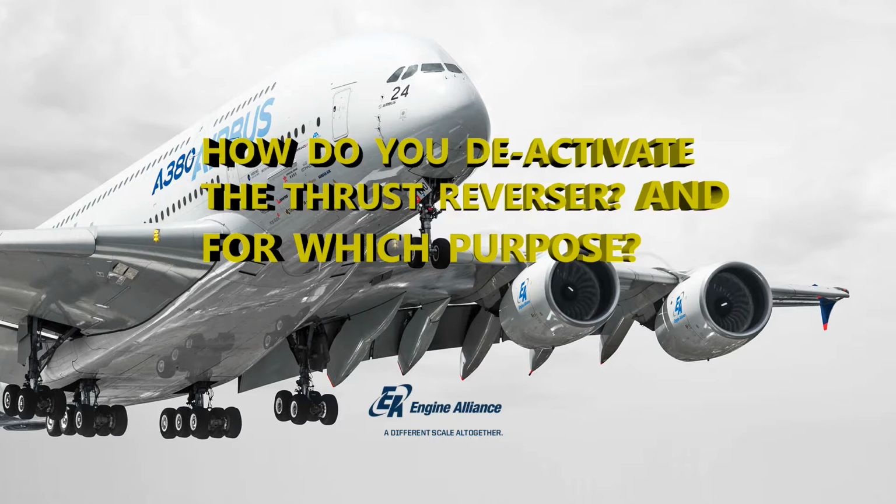On the electrical deactivation. Now, mechanically deactivating it, you're going to have to go into the latch access panel, and actually secure that so that you're blocking it, so there's no way it can mechanically be activated. All right. So again, be careful about opening and closing, just for your safety. Make sure you stay clear of its potential path if it ever got activated inadvertently. But hopefully that won't be the case.